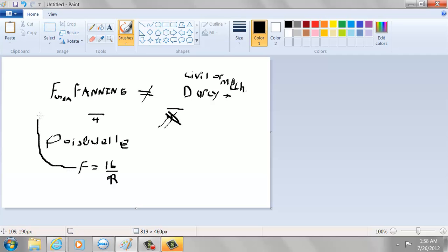Most of the equations from now on that are using a friction factor will be the Fanning friction factor. This is coming from a fluid mechanics book for chemical engineers. So we will be dealing with a Fanning friction factor more often than with a Darcy friction factor.